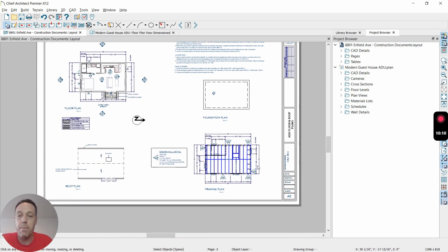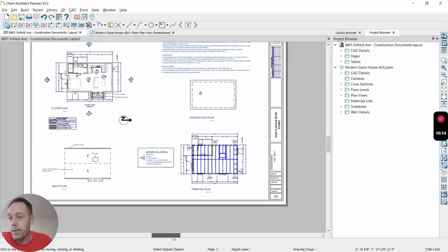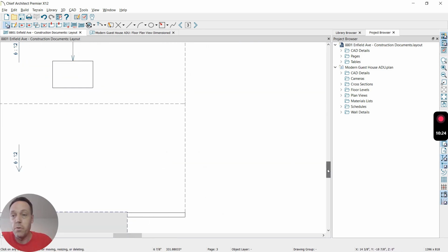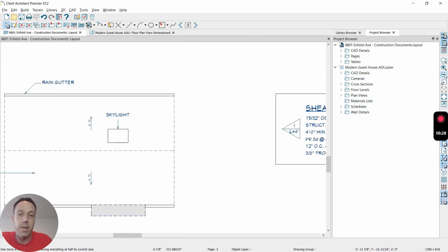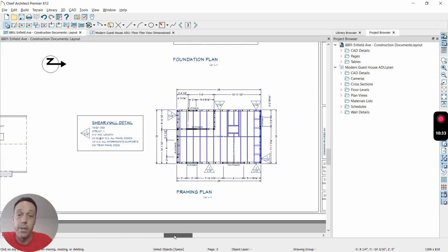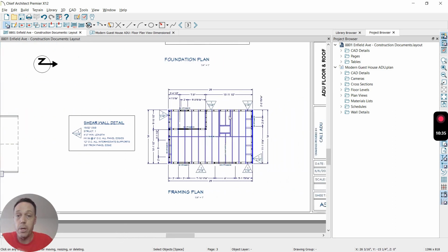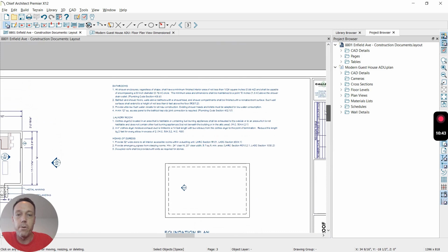So we've created that for our client here, and we're just using a Class A rated asphalt shingle roof, pretty standard. It's going to last 30 years. The skylight's called out on our roofing plan for the plan check engineers. We're showing the wall details and where the walls are going to be, the size of lumber we're going to use for the walls, etc. So all these details the city's looking for when you submit plans.